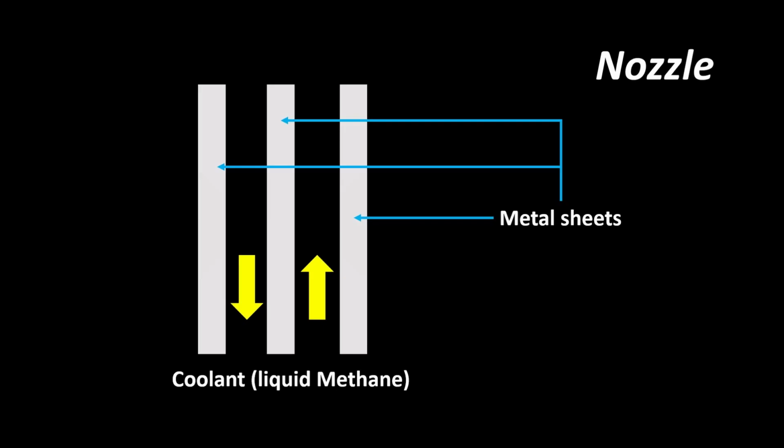And the nozzle has even 3 layers of metal alloy in its wall, and between them 2 channels for methane. In the inner channel, the liquid methane flows down to the very bottom of the engine and gets warmed by all the heat it absorbs. To get all this warm methane back up to the preburners, the outer channel exists. Have you ever asked yourself why the nozzle of the Raptor doesn't glow like the one on the Merlin vacuum engine?